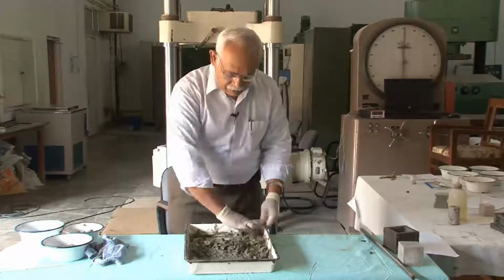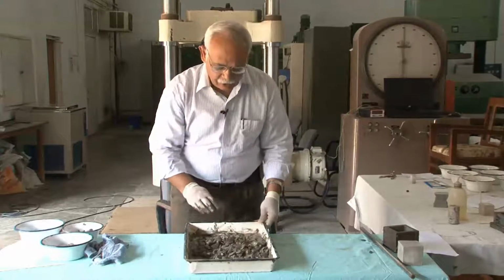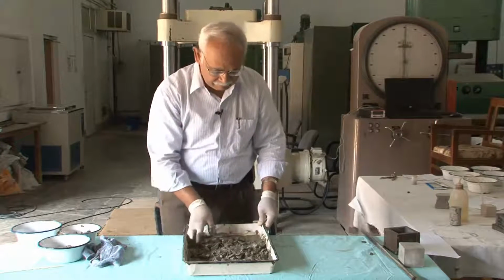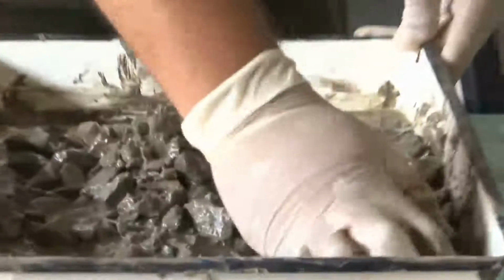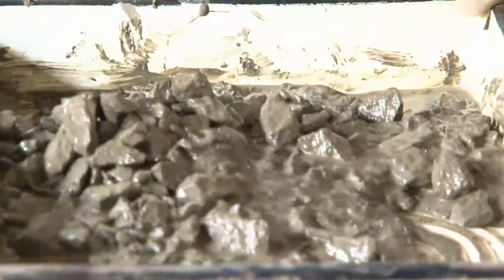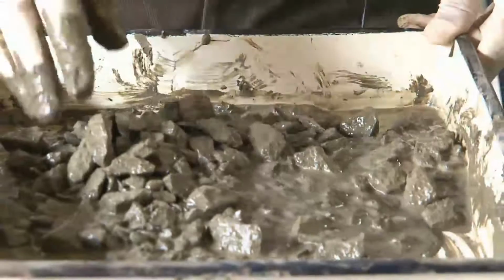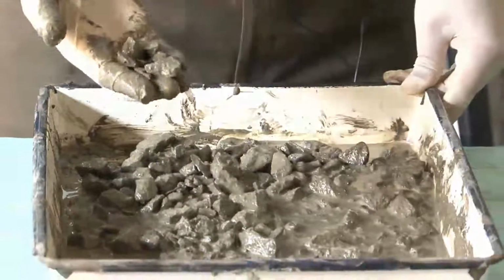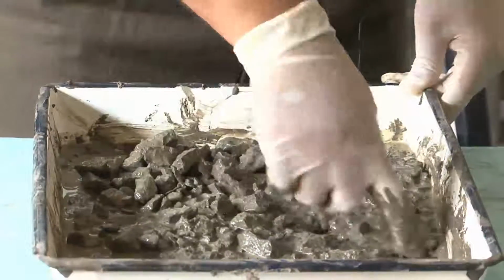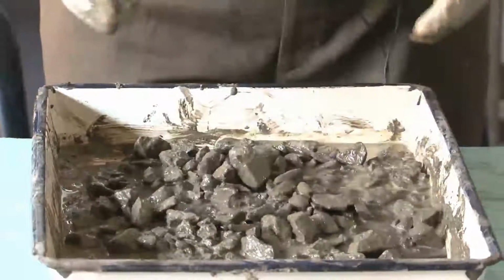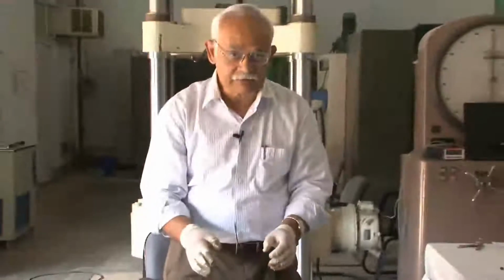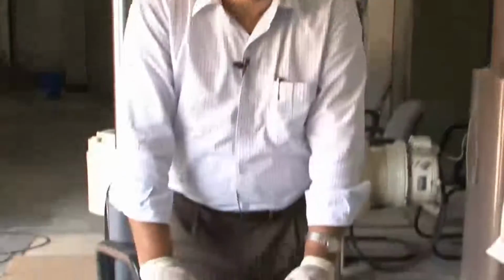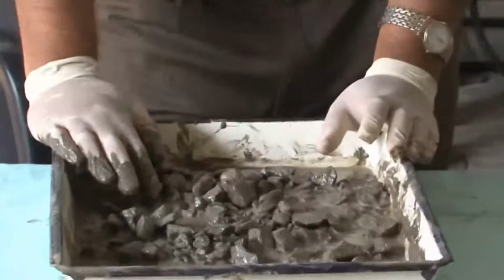When we look at the concrete having a super plasticizer as in this case, we should be careful to notice that the concrete does not segregate. That is, it should not happen that the coarse aggregates become separated from the mortar phase. So, in this particular case, we are seeing signs of segregation in the concrete mix, because the chemical admixture was added without a consideration to segregation.